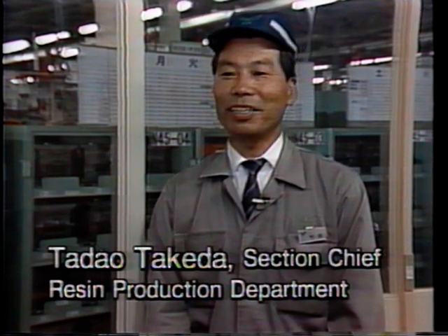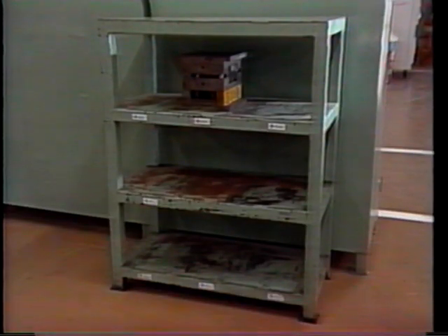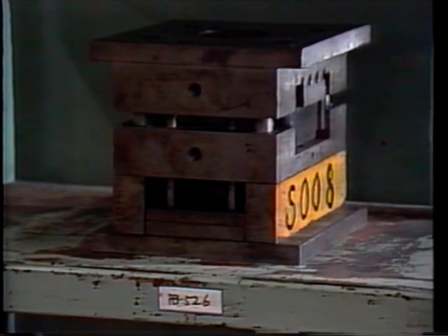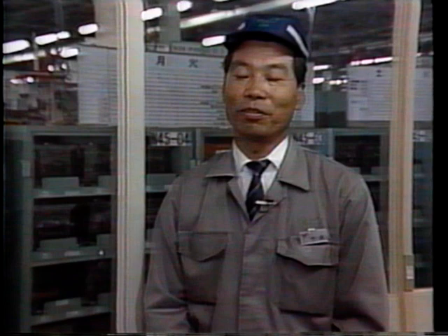We decided to devise a completely new storage system because of the number of faulty products we were getting. We realized the problem was that we were using the same molds over and over without cleaning them properly or taking care of storage. Various workers made suggestions, and we gradually came up with our jewelry box system. We established storage rules. For example, the direction the molds were to face, and strict horizontal and vertical shelving.